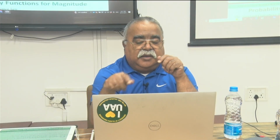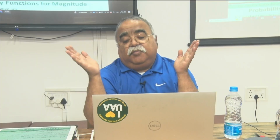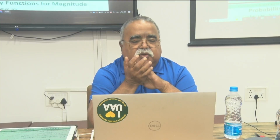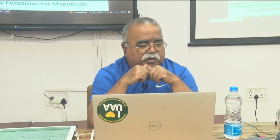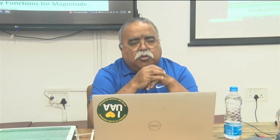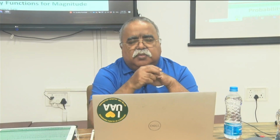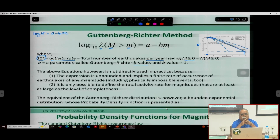We cannot consider earthquakes of 0 magnitude, and suppose a particular fault has a maximum magnitude of 6.5, so we are only limited from 5 to 6.5. That is why our relation is a bounded relation. The Gutenberg relation is an open relation from the zero magnitude to any magnitude possible, but if it is a bounded magnitude, then we call it a bounded Gutenberg-Richter relation, right?